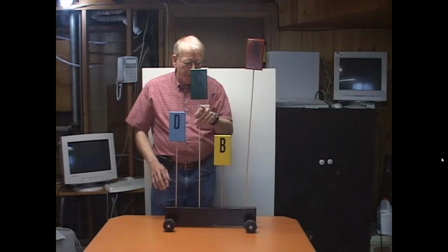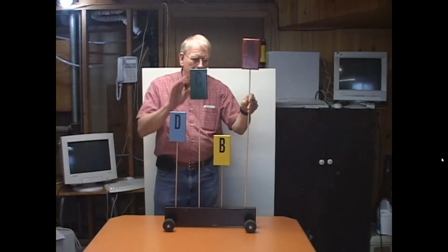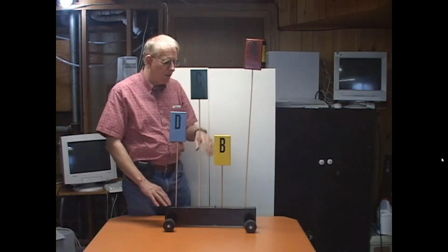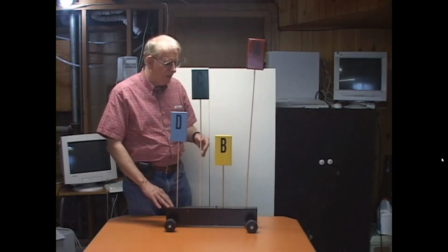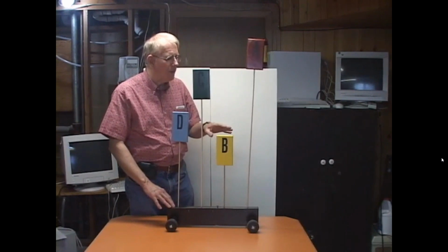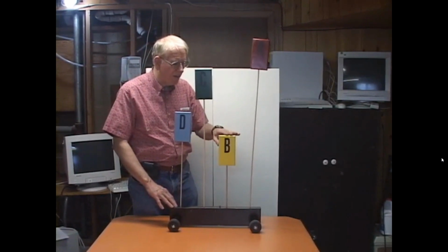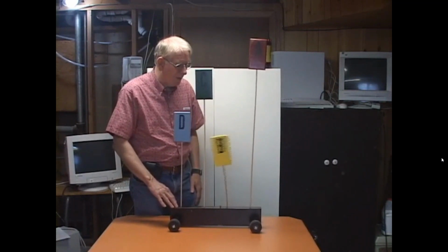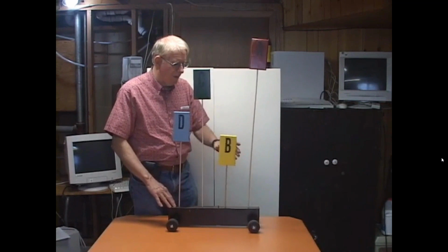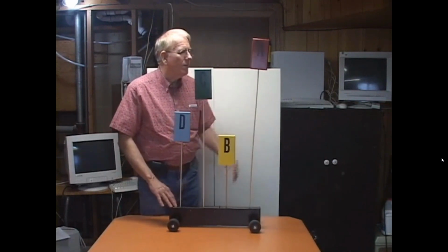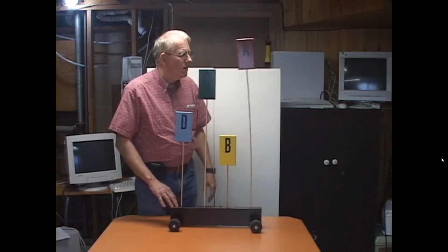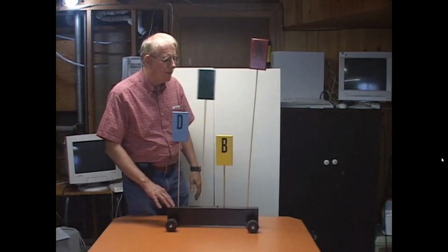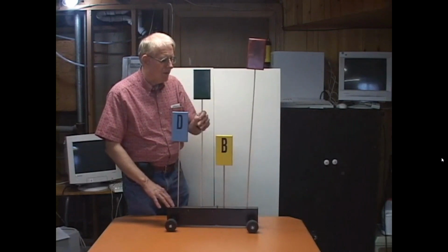So if the ground motion is the same as the resonant period, resonant frequency of one of these buildings, the amplitude of building motion will build larger and larger. So if I move the ground very rapidly back and forth, I'm getting a resonant frequency near this one. You see the amplitude there, it's very large. And if I go very slowly, all buildings move large. And you can also go at intermediate frequencies. This one.